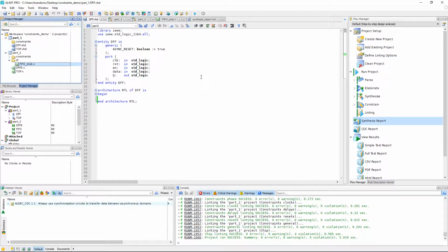In fact, block level constraints can even facilitate analysis of largely hierarchical designs, as once individual blocks are verified separately, those top level blocks can be abstracted via constraints, which allows the tool to only focus on those potential input-output issues between the top layer and other components of the same design. However, you wouldn't have to worry about constraints for FPGA vendor primitives, for example, as we provide those predefined and with precompiled constraints already.